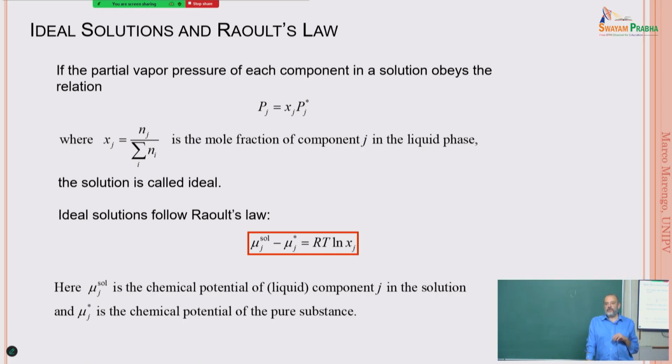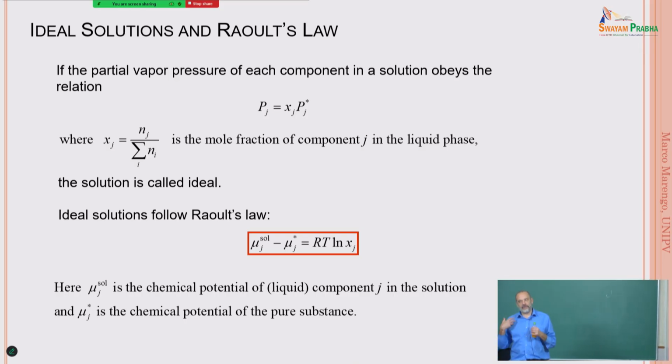A classical multi-component problem in a heat pipe is the fact that inside the fluid you have dissolved gas. You have the liquid, for example ammonia, water, propane, acetone, whatever, but some air gas is inside. You did the vacuum, you tried whatever, but some gas is there.